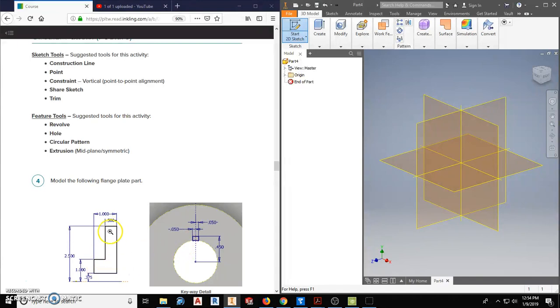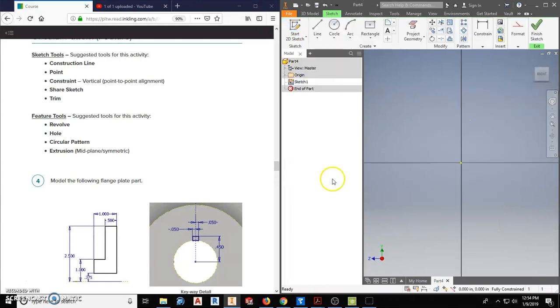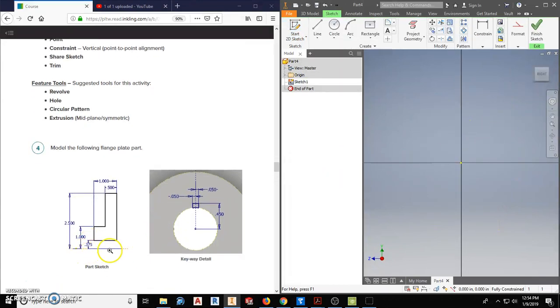We're going to create this little flange, and then we'll do an extruded cut through the detail. The extruded cut's not that big of a deal, so we might just skip it. I'm going to go ahead and hit the YZ plane there for the right side. And we're going to draw out this line. So first things first, I'm going to just draw the profile. I'm going to start at the origin. I'm going to go over one.